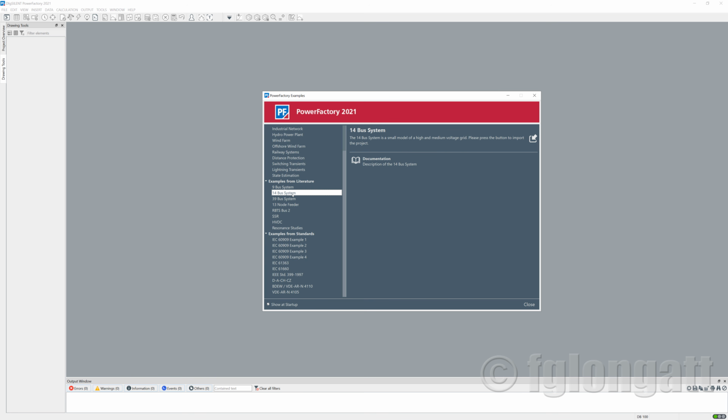Here, this is the IEEE 14 bus bar. This is another test system that is very well known for scientists. This is the IEEE 39 bus system. This is a really simple model, but is very interesting for analyzing transient stability. And PowerFactory people include here a test feeder. This is for distribution. This is the classical IEEE 13 nodes test feeder. Here we have something for the Rowe-Billington book, okay? This is the Rowe-Billington test system. This is the 2-bus system.